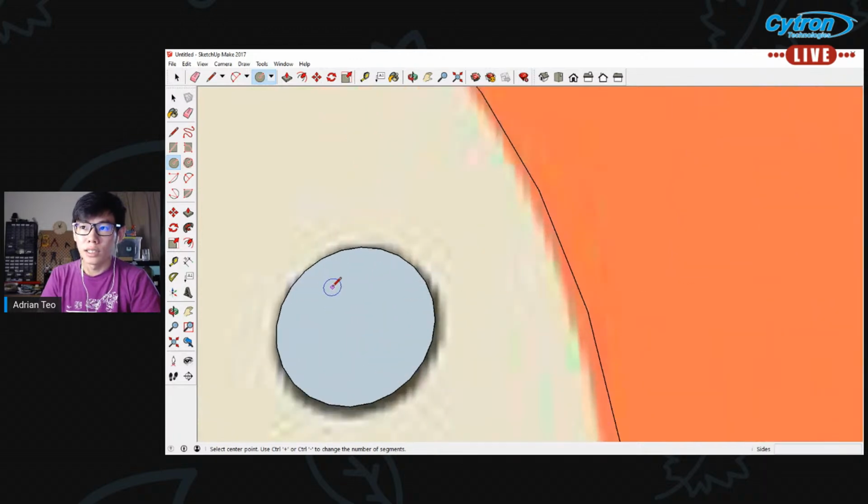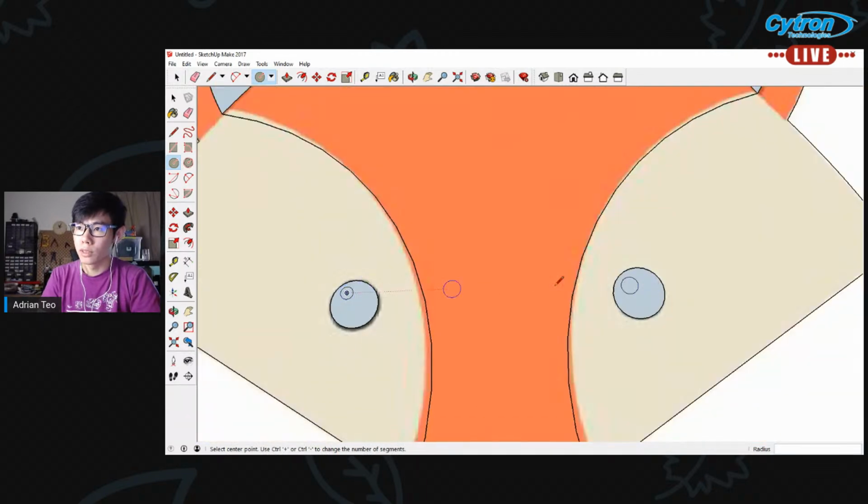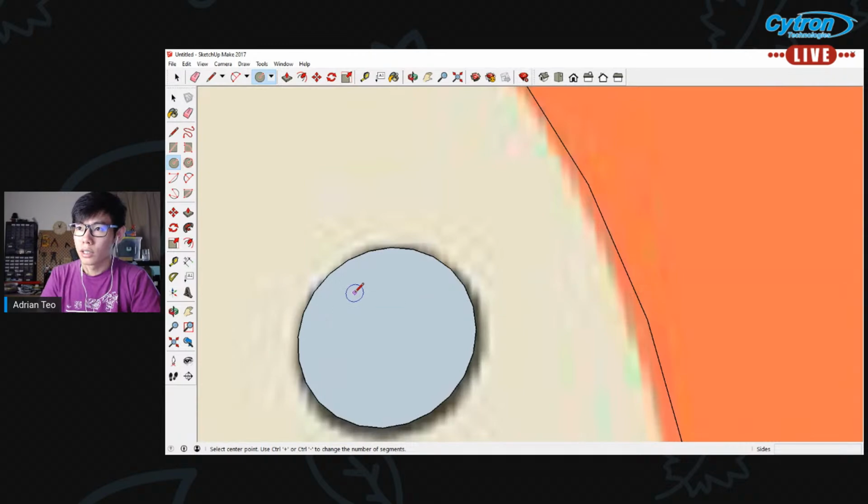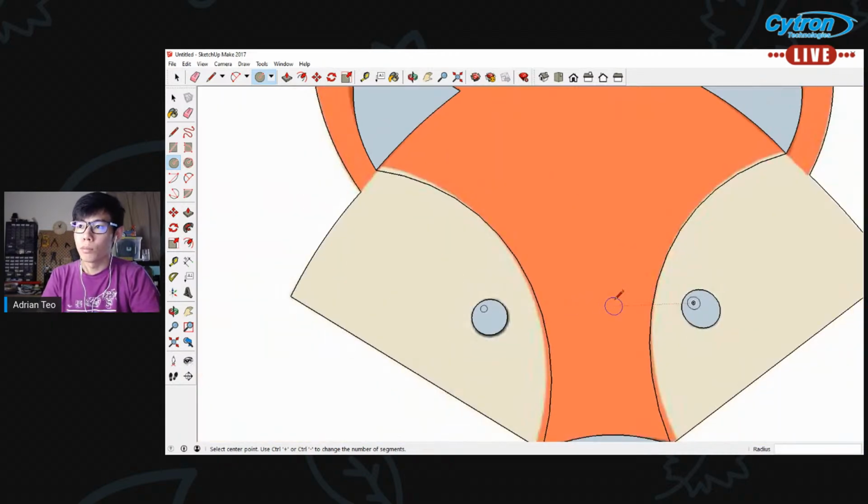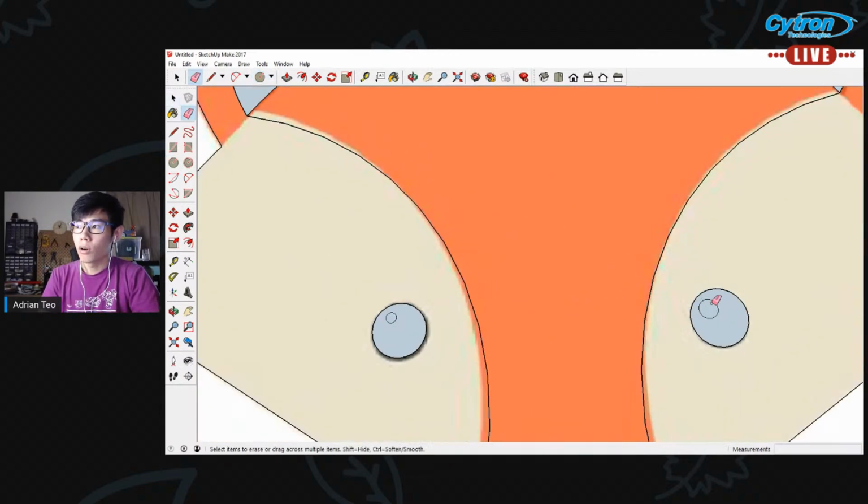I can tell you that it doesn't really matter. You can make sure that both of these circle sizes are the same. How do you check? You go and create this circle at the bottom right, and you'll be able to see the size here, the radius. You can set a specific size to make sure that both sides are the same, or you can just use your artistic sense.